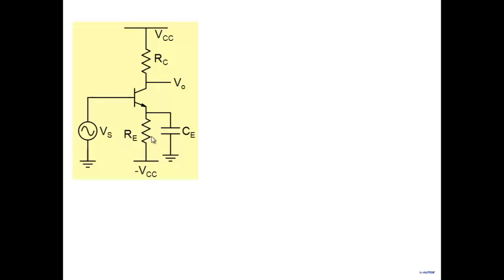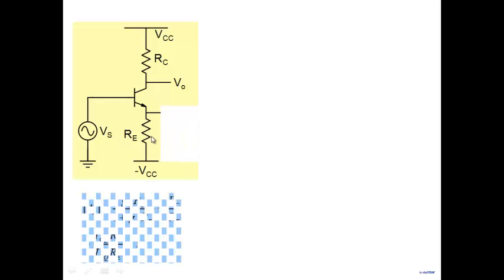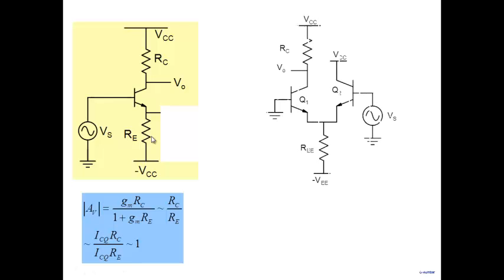In that context, you've already seen the solution in our midsem, a circuit like this. We had this particular problem. Note, there are no capacitors anywhere. Can you see RE? But I've not connected any bypass capacitor. And many of you got the answer right. The gain of this particular stage is 0.5 GMRC.